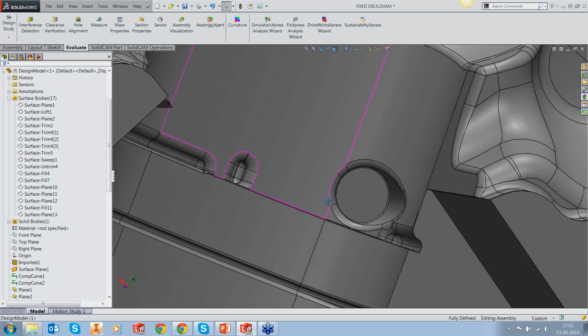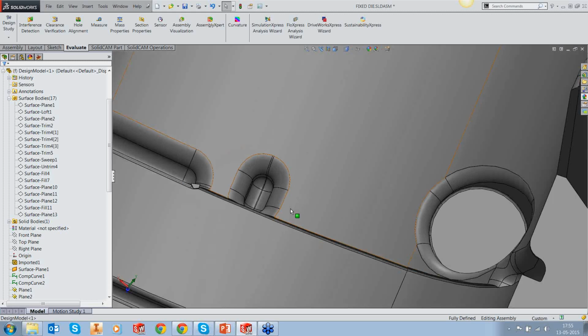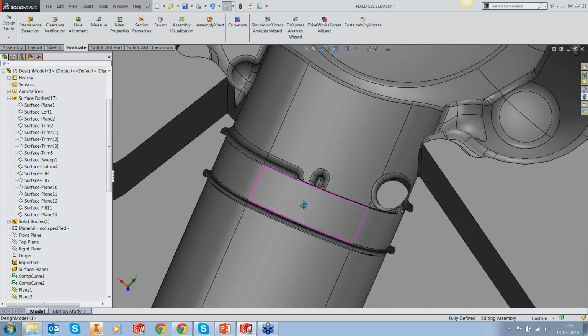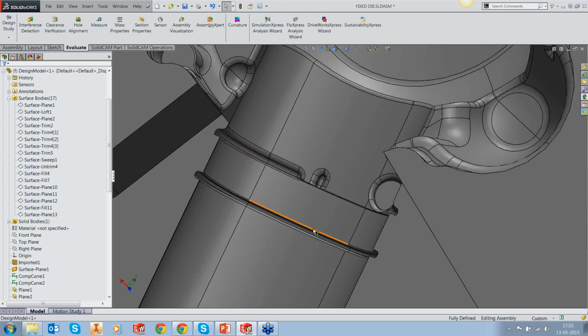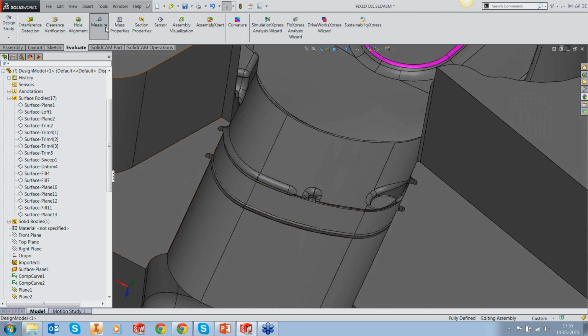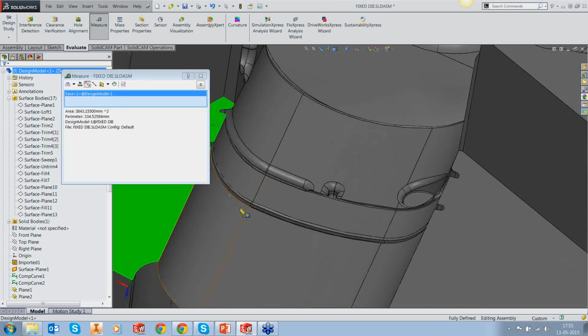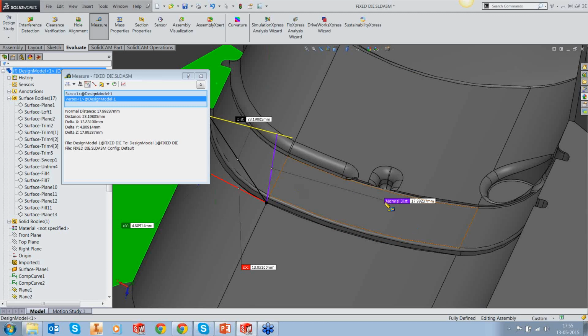Also, I have another small area out here, which again doesn't make any sense to keep for machining. This also needs to be closed. So I was referring to areas that need to be closed on my slide, and these are exactly those areas. For example, this particular rib, if I calculate the height it needs to go, is about 17 millimeters.